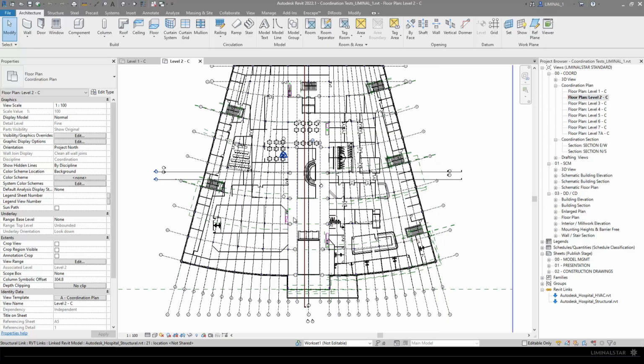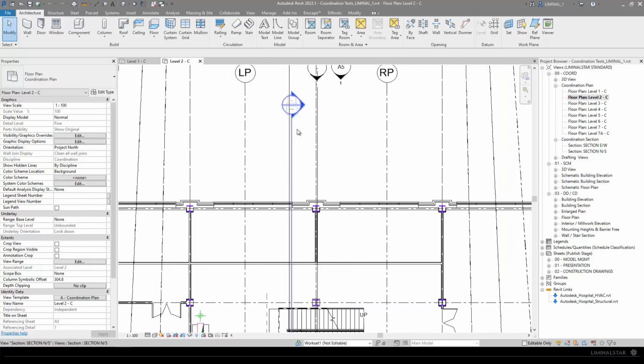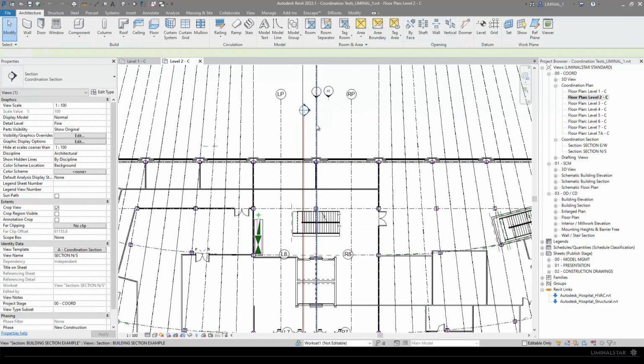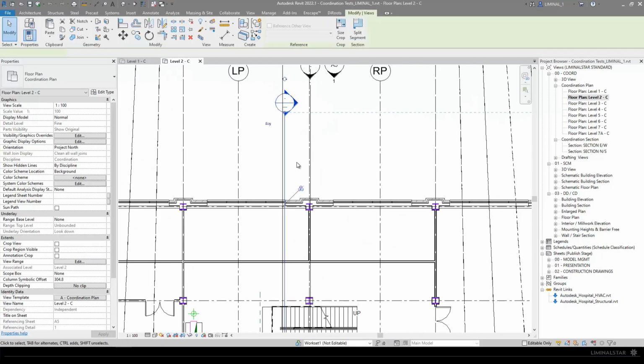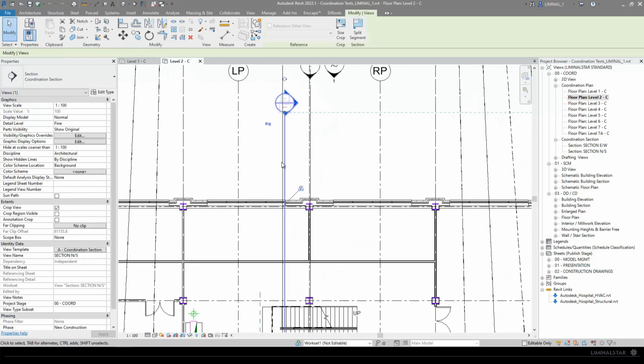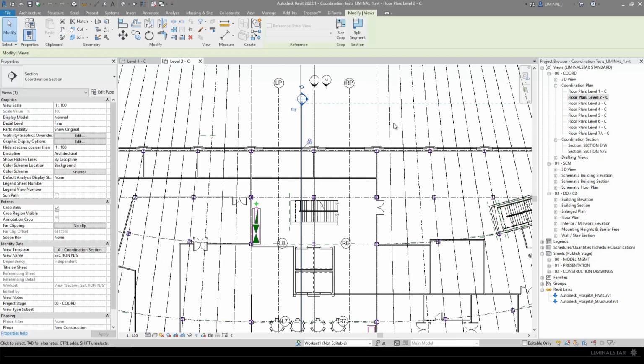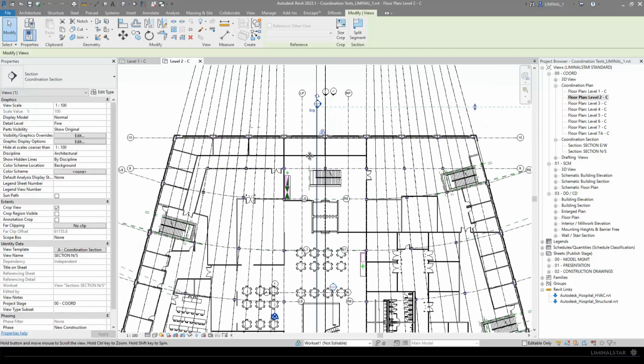settings on it. So for example, I've set up a view filter to make these coordination sections red, and that's so I can easily identify something that I'm allowed to move, or it's okay to modify its settings, because this guy is just called section northwest. It's meant to move around. But if I wanted to ensure that nobody messed with this one, then maybe I'd want to throw my name at the end of it.